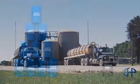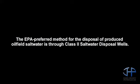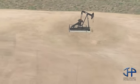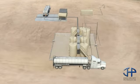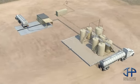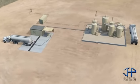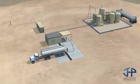The produced salt water must be disposed of properly. The EPA preferred method for the disposal of produced oil field salt water is through Class II saltwater disposal wells. A disposal well is typically an existing oil or gas well that no longer produces hydrocarbons. This is the only approved method for oil field saltwater disposal, and only wells that meet strict standards for construction, testing, inspection, monitoring, and record-keeping can be classified as Class II disposal wells.